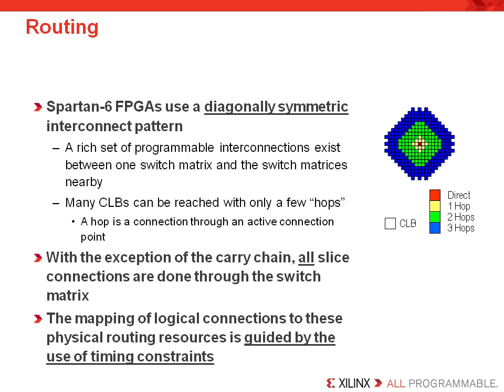The Spartan-6 has routing besides carry chain logic. It is routed through the switch matrices. While understanding the interconnect structure is seldom needed, this diagram is meant to describe the population between slices and CLBs. You see, in between each CLB is a switch matrix, which is designed to connect to other switch matrices as well as neighboring CLBs. The possible interconnects are called PIPs, or Programmable Interconnect Points. Please note that proper use of global timing constraints, which is explained in the Essentials of FPGA Design course, is going to be required for you to obtain optimum speed.